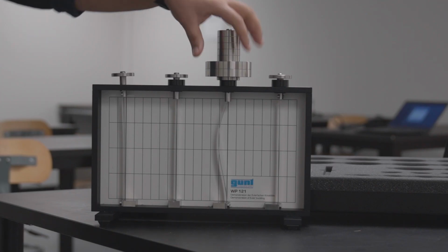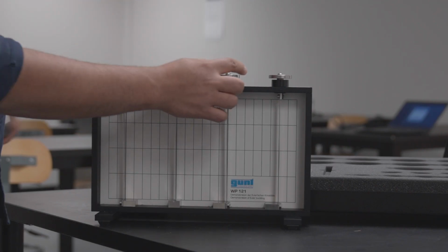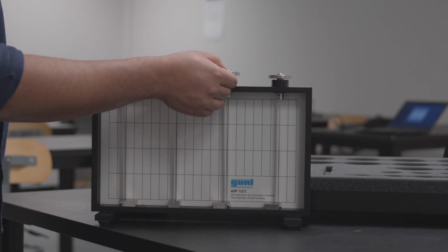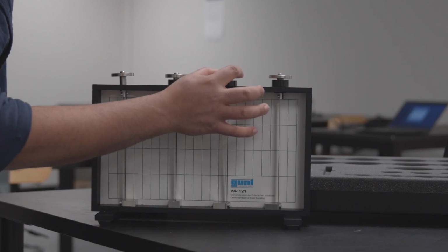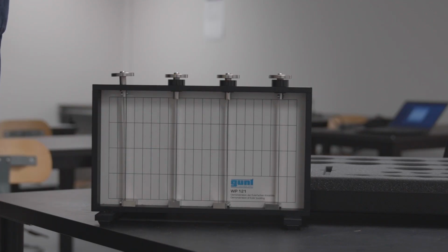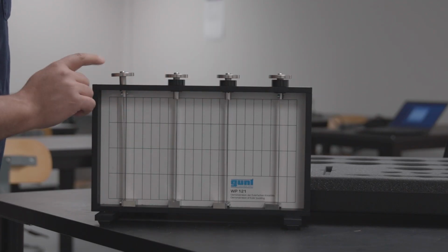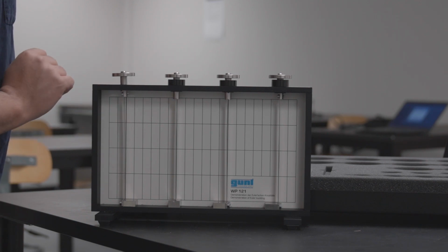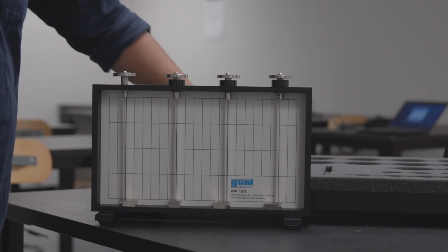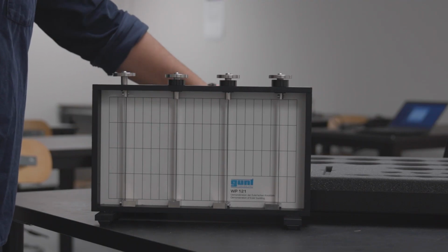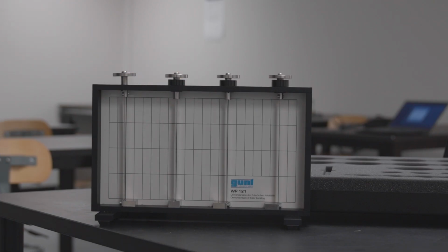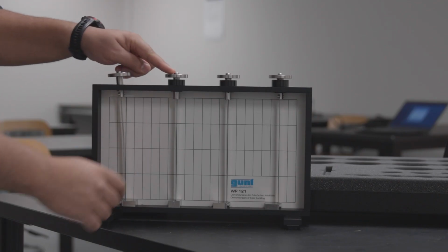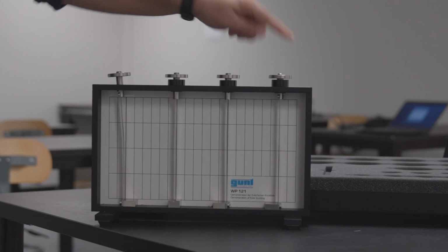So the buckling happens when this part of your support actually hits the black part of the frame, right? For these first three. For the first one, buckling happens when you actually hit the frame as well, so it has to go all the way. There's a little bit of a difference in buckling, but the idea is essentially the same. Based on compressive loads, your beam is going to buckle based on the type of support you have.